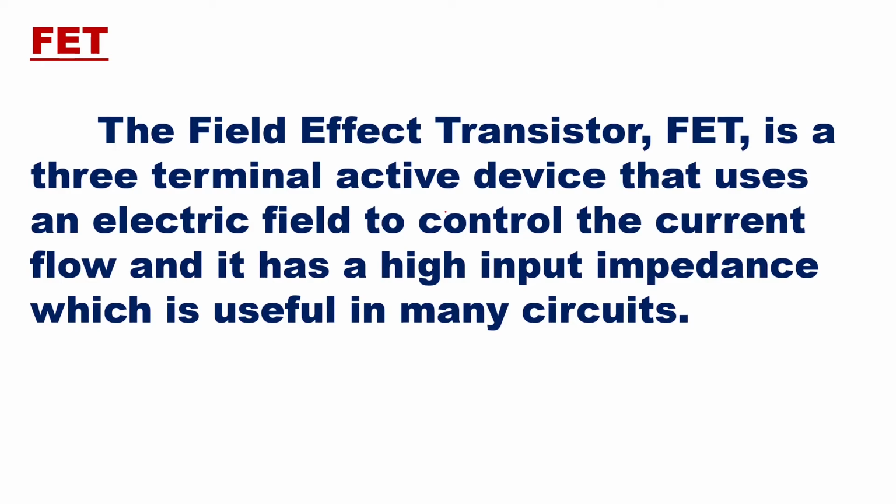It has high input impedance because at the input you are going to apply a reverse bias at the gate, and the gate-source voltage, that electric field, is going to control the current which flows between source and drain. So this is the definition for FET.